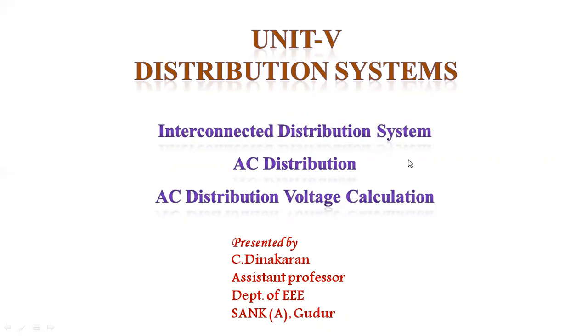areas, etc. In the radial distribution system, the major drawback is that if any fault occurs on the feeder, all the consumers are affected by the power cut. One more drawback is that the consumers at the end get affected by serious voltage fluctuation due to the variation of load. The radial distribution system is fed by only a single distributor and the voltage drop is more. The radial distribution system is not reliable and not an economical system.